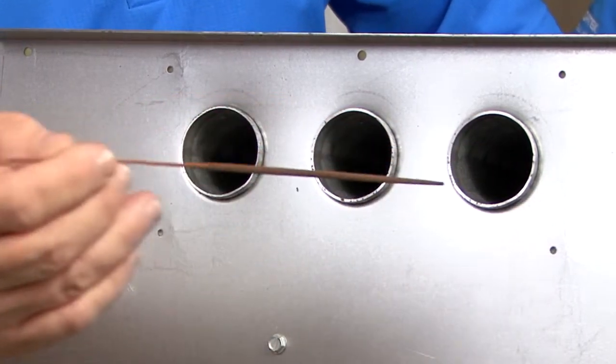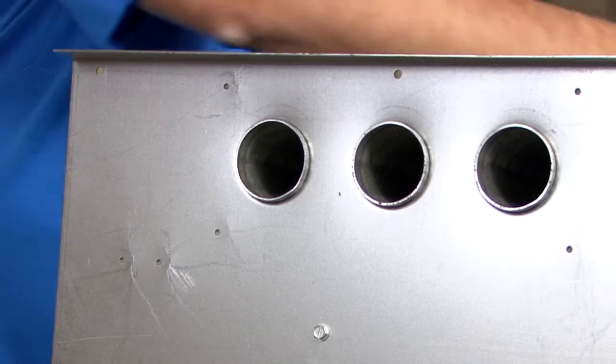So what are we after here? What are we after with this test? Are we after the smoke just literally getting sucked away from us? Are we after the smoke blowing back in our face? Well, both. If the smoke blows right back in your face, then we're obviously blowing air into that heat exchanger from the main air blower, and we don't want to do that. And secondly, if you've got a breach in the heat exchanger, it could be creating a vacuum at the breach, and it'll actually cause the smoke to get sucked away from you. So either way, that smoke up inside that heat exchanger should just linger in there because it's got nowhere to go.